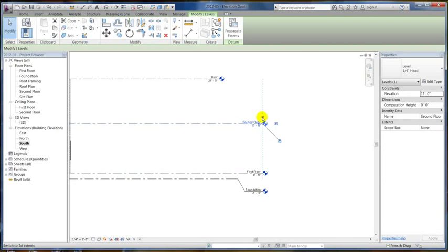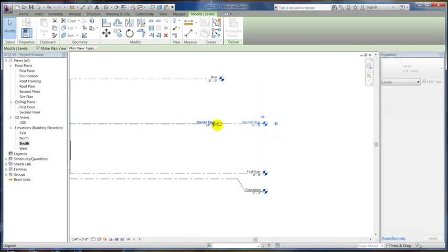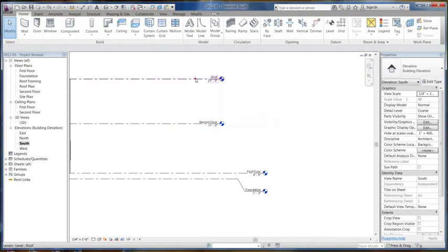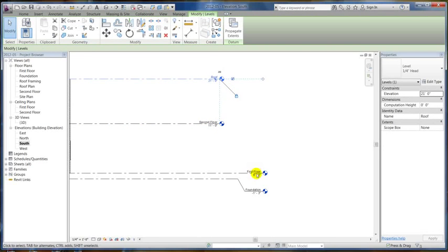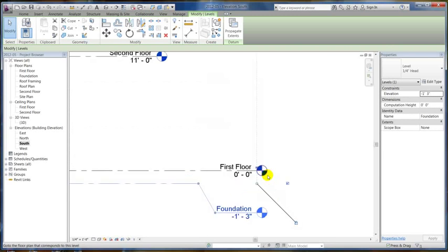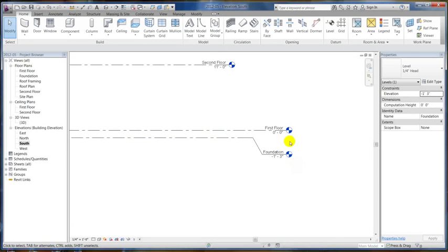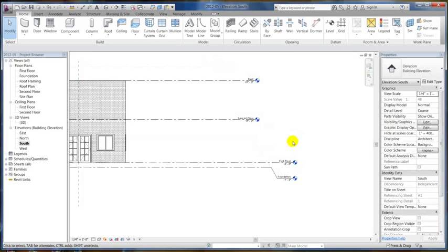So if I click on that, change that to 2D, and I can move that level and I can line it up. Now those 2D levels are locked, and then these will still be 3D, and I can check that to 2D, and that one's obscured. You can see it right there. Make that 2D. 2D levels can lock with each other, 3D levels can lock with each other.